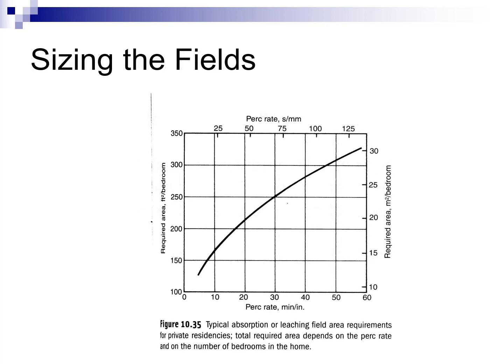And what that percolation test result does is allow me to figure out how much area of fields I need. So this is actually the chart that's used for sizing the fields. What I want you guys to notice, and I mentioned I'm working in minutes per inch for my perk rate, but the area is given in square footage per bedroom, or square meters per bedroom.